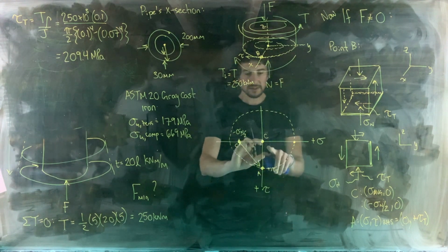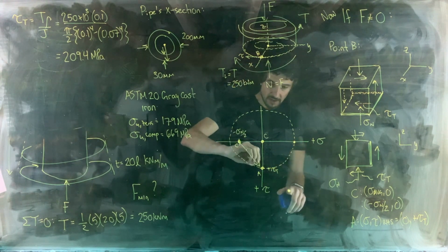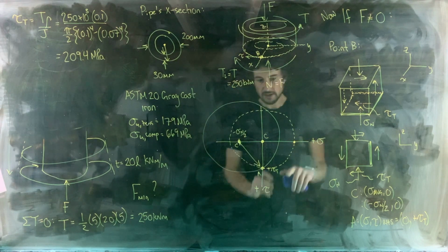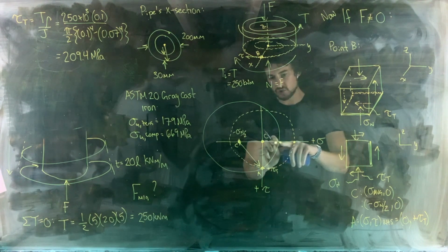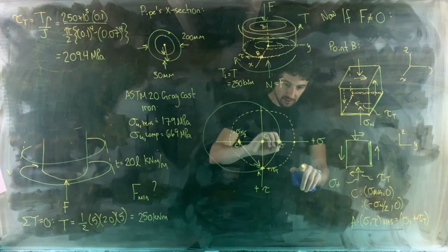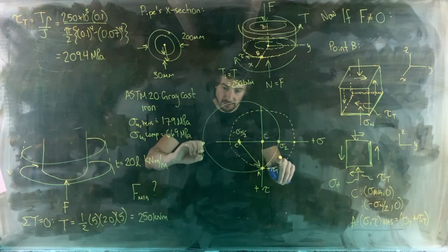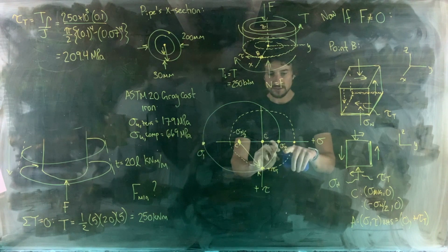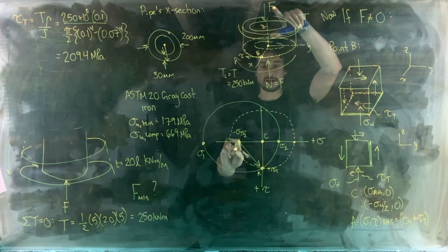All right, so since we've kept A at the same location, move the center of our circle over. Now when we draw the circle, the largest tensile stress present has dropped to this value, sigma 2. And I'm calling it sigma 2 again because the larger magnitude principal stress gets labeled sigma 1. So sigma 2 has dropped due to introduction of that compressive load.